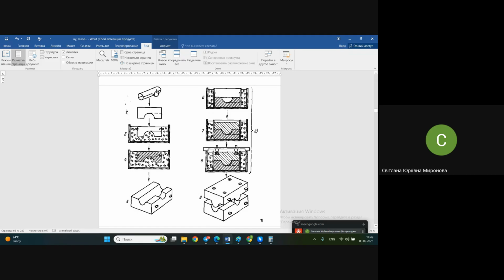We place the real die block in a special box and so on, covered with separating elements in order to prevent adhesion and in order to imitate the thickness of the part that will be here next. And fill again with the metal.